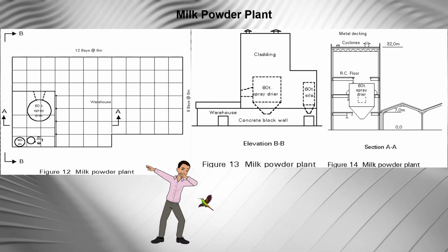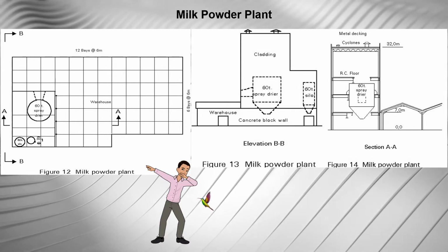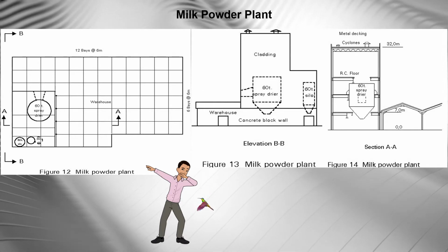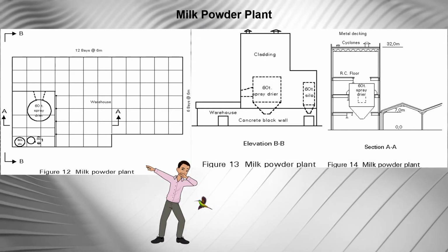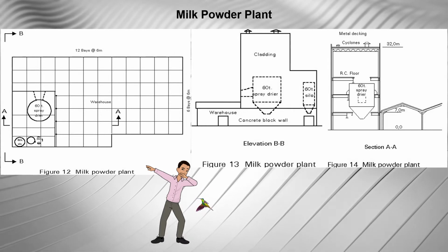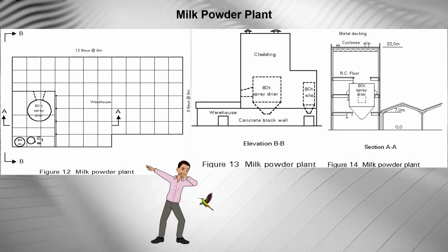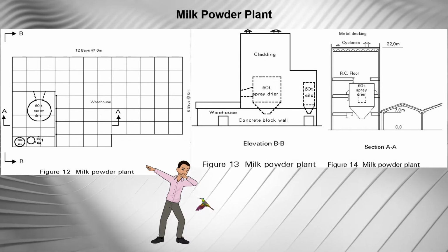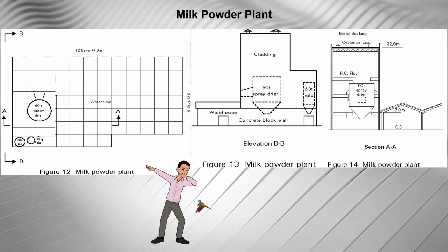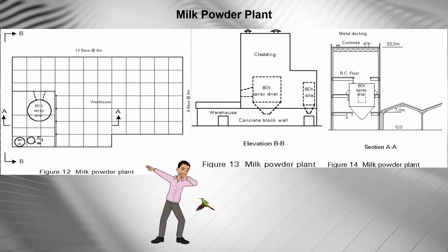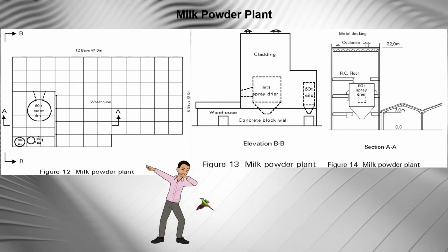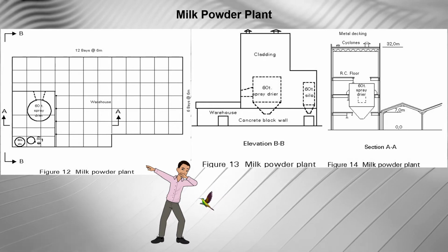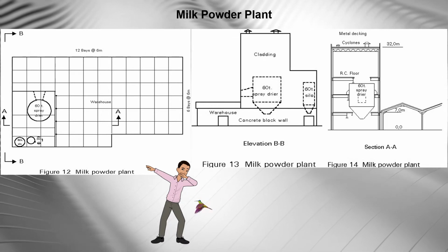The tower and annex are framed in structured steelwork with composite concrete floor and steel cladding. The warehouse typically has multi-bay short-span portal frame carrying pressed steel purlin and asbestos cement or single skin metal cladding. The spray dryer is a 10 meter diameter stainless steel drum, 14 meter high, supported at several floors. Milk and hot air are injected at the top and the dry milk powder collects in the hopper bottom. From there it is conveyed to the silos of the packing plant.